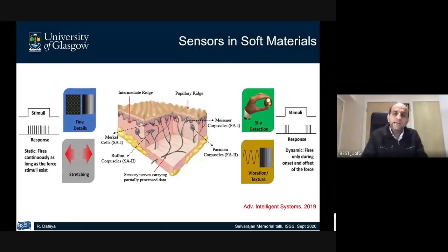All right. So slow adapting, in a sense, is when you take a typical task of pick and place. When you are grasping something, at that time it's a dynamic thing. So your sensor has to respond to dynamic events, and normally piezoelectric type sensors are suitable for that. But if you are holding something for a long time, that's where static force sensing comes into the picture, and capacitive type sensors are suitable for those events. Then on top of that, there are temperature related receptors, then pain related receptors, and this all comes as a package when you look at the skin over the entire body.